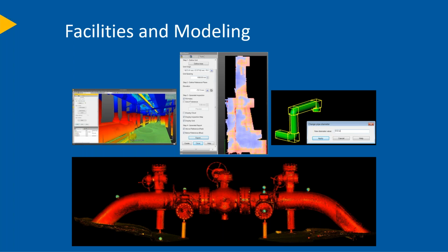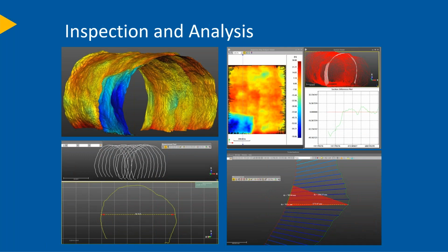The middle picture in the top is an example of scanning a floor to get a floor flatness. So this is quite popular for buildings where it's critical to get flat and level floors for bringing in special equipment or locating areas such as doorways and elevator shafts. Scanning makes quick work and makes it able to go and identify the entire floor, not just samples of it, and identify what's going on and how bad things are or good.